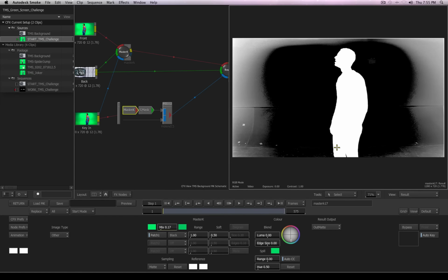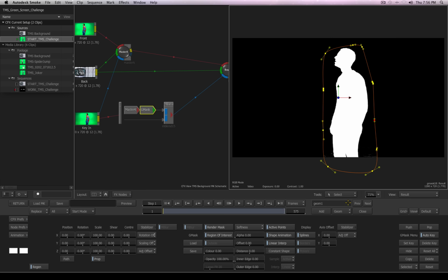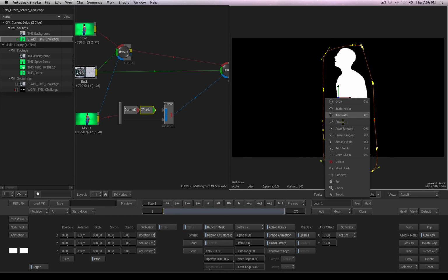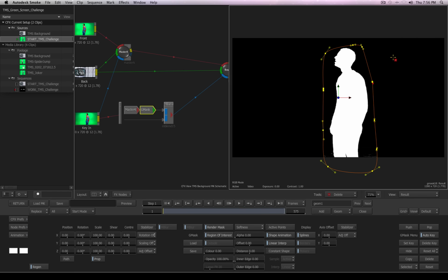Of course, I'll close it then, and then we'll click on it to set it, and I'll choose Region of Interest. Now, it looks like I've got more control points than I really need. So this is what's great: I can switch my tool to be any one of these other tools. I'll choose the Delete tool, and then I can go into the player, the viewer, and just start double-clicking or clicking on these control points that I want to delete.